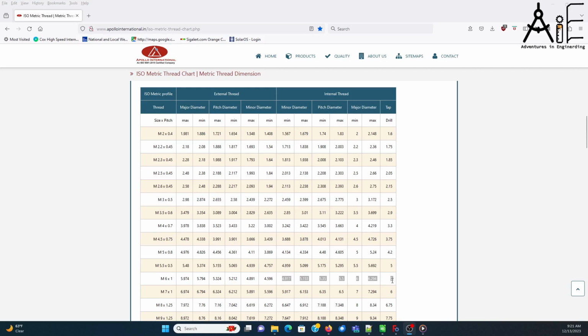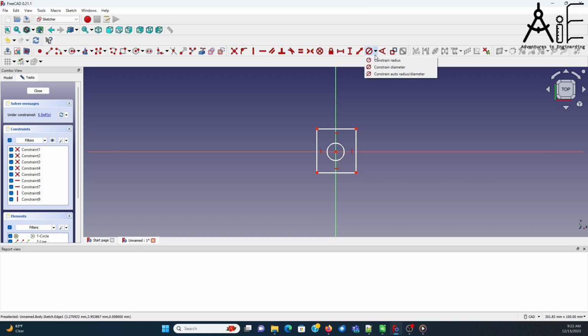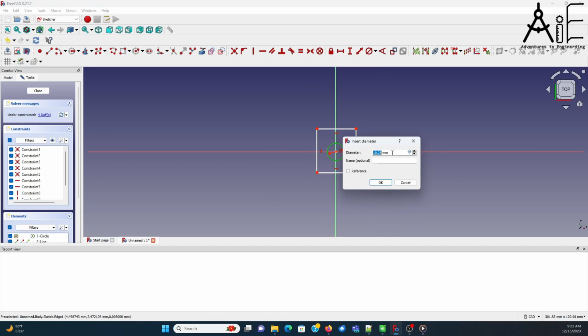They say to tap it at 5 millimeters, but I say tap it at what you want your minor diameter to be. So in this case, I'm going to go with 5.2 just to make it reasonably loose, and so the threading tool doesn't have to do as much work. So I will start with a 5.2 bored hole, and then I'll use the threading tool to cut it out to 6.2 or 6.3. Dimensions, I'm going to use a diameter of 5.2 as the chart showed.